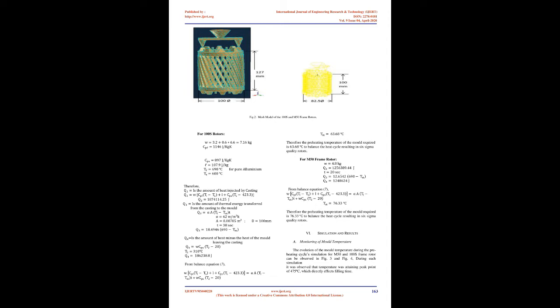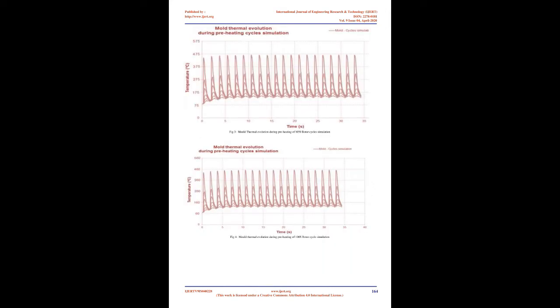The process parameters which are critical and can affect the process considerably for producing defective castings are pouring temperature. Pouring temperature generally varies from 650 to 800 degrees Celsius. When we pour aluminium alloy, its fluidity is completely dependent upon pouring temperature.